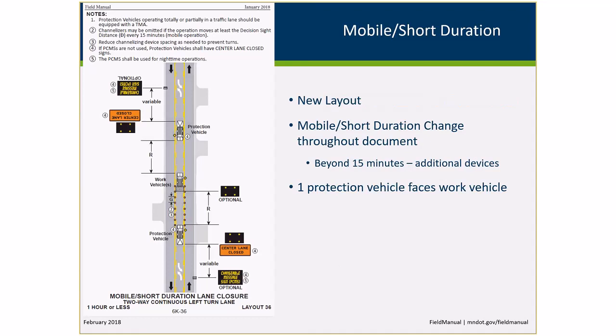One thing to quickly mention about this overall situation is that all the mobile layouts that were in the field manual before, we've now converted to mobile short duration layouts. Mobile layouts are meant to be used for up to 15 minutes. Short duration are layouts that are meant to be used up to an hour. We had previously had a lot of requests to open up the mobile layout duration. Instead of 15 minutes, can we use 20? Can we use 25?